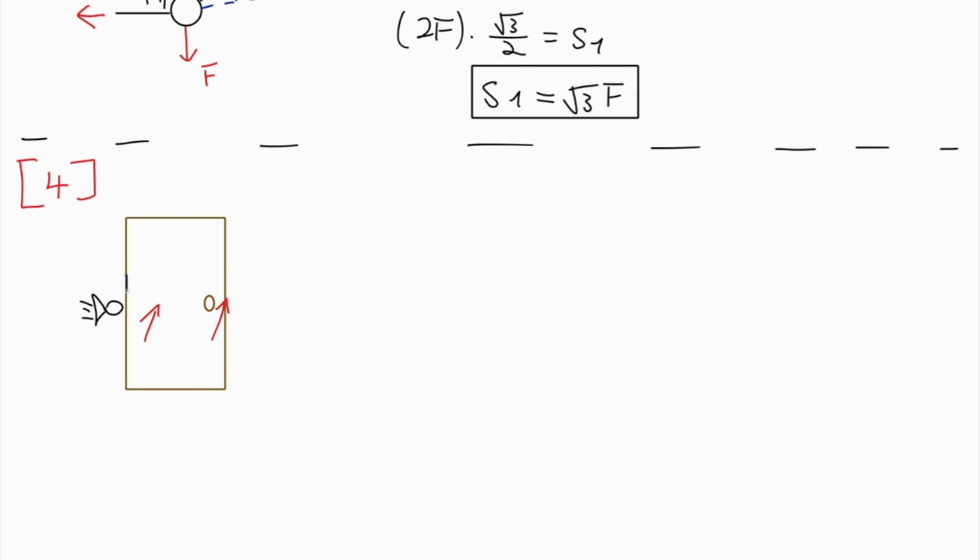So when you push close to the hinge, this is your lever arm right here, right? L1. And this is much smaller than your second lever arm if you push at the second point. So the moment you generate is much, much less, and hence your force has to be higher. Okay, so remember, moment is a force times a lever arm. So your lever arm being shorter implies that your force has to be much larger. That's why all the doorknobs you ever see are always going to be as far away from the hinge as possible. Okay, this is just so you can push the door open easily.